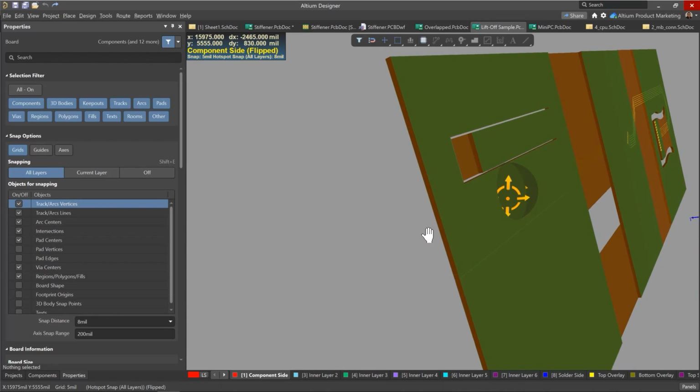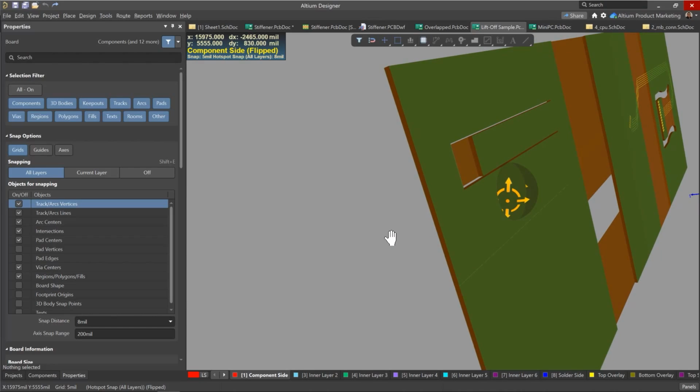So by working with the priorities in the properties panel, you're able to define shapes that would have been incredibly difficult to define in the past, and very easily define them and work with the different types of layer stacks. We also looked at adding the adhesives in the layer stack manager.